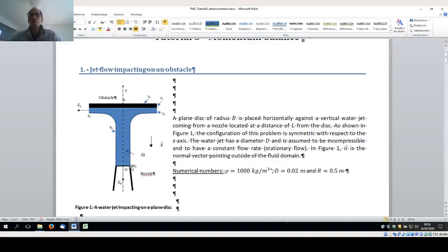Here, the simplest way is to identify the inlet, which is the output of the nozzle, where the flow is getting inside, and the outlet, which, because there is axisymmetry of revolution, will be the S1 surface, an annulus at a given distance from here. And here you have your circular plate, a circular disc, which will be in contact with the water.